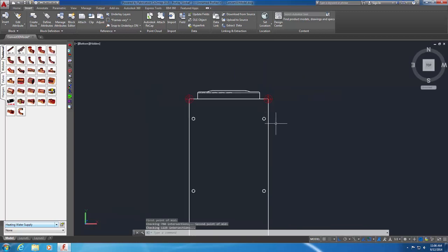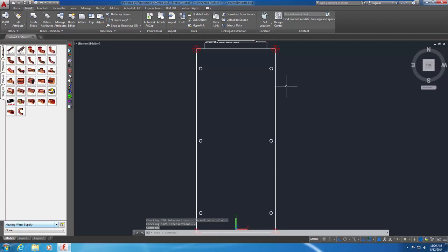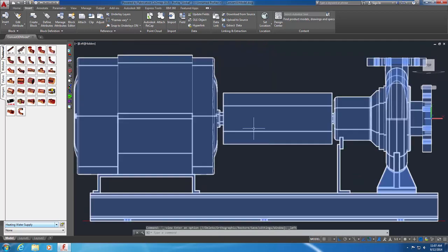The snap point block is inserted at the middle of these 2 points, placing it directly in the center of the pump base bottom surface. Change to a left view. Next, you'll insert a block named ConDef to define a suction or input connection point for a supply pipe.